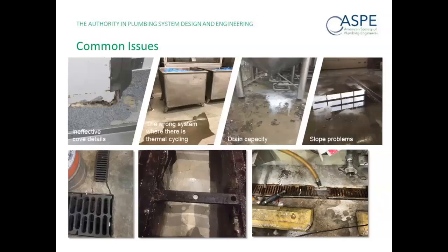Right, because you can see not just the square drain, but the rectangular trench on the bottom left. I can see that stress crack between those two corners, and that's an exact result of that thermal expansion we talked about before, right? Those materials are expanding and contracting at significantly different rates. Exactly, and concrete shrinks over time, so that longitudinal splitting, or the shear force, essentially, when you have a 90-degree transition point, it will split at that point. So it's just something to be conscious of.